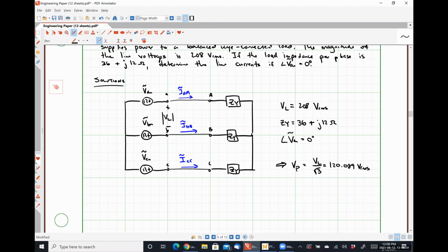The 208 is the delta connected or the line to line voltage. The 120 is the Y connected or line to neutral voltages, so that you have access to either of those things depending on how you connect stuff to the panel. Yes? So if you throw your multimeter on it and you touch 2 different hot lines, it's going to measure 208 volts. Right. But if you go from a hot line to the neutral, it'll measure 120.